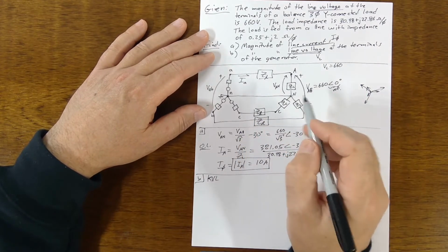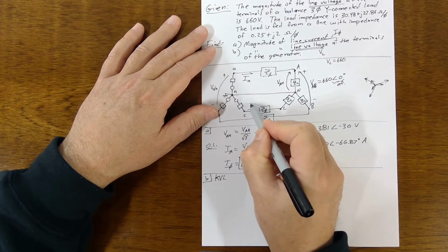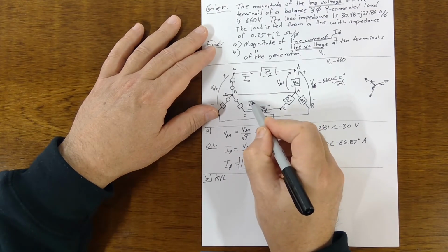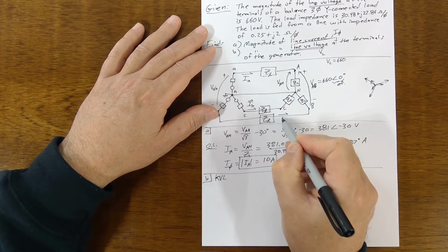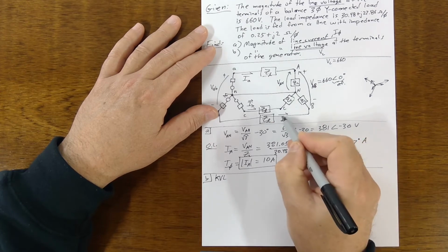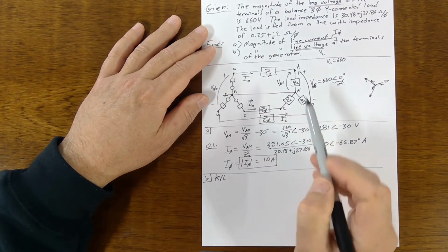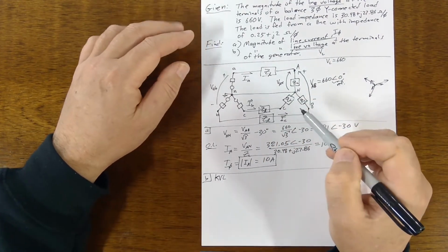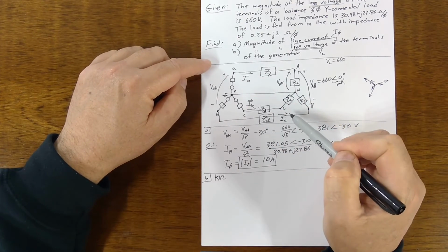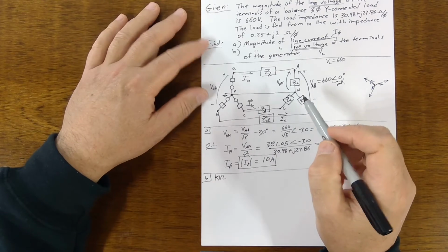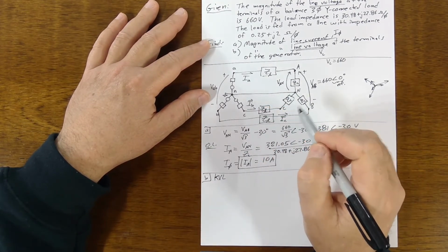So first of all, there's 3 phase currents, and there's a convention on drawing these things. We draw them all that way, going from the source to the load. So the arrow's going that way. Now, it gets a little confusing because we've done this with DC circuits, and when we choose all positive directions like that, we know that one of them will have a negative value, and that will happen here. At least one of these guys must have a negative value.